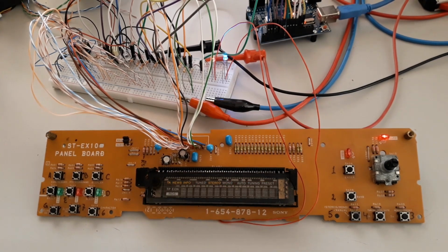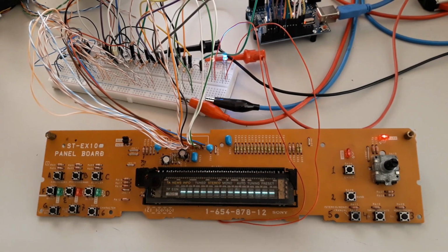As we have two key lines, we will use two analog input lines in the Arduino to collect the values present on the lines. Each row of the switch originally had 6 resistors, and I added 2 more, one as a safety resistor and one as a pull-up to the plus 5 volts DC.